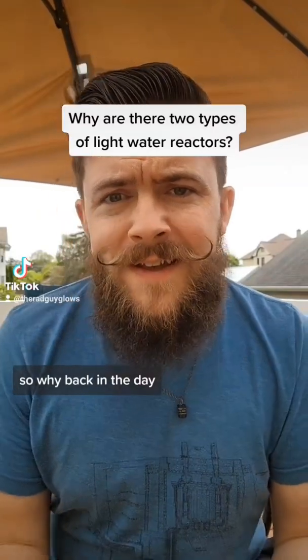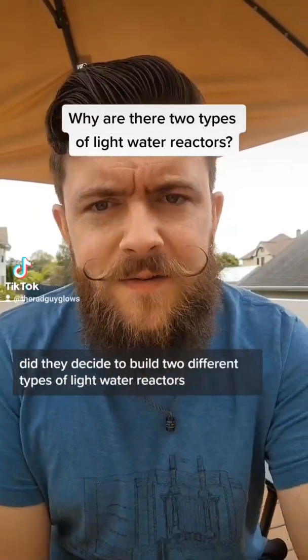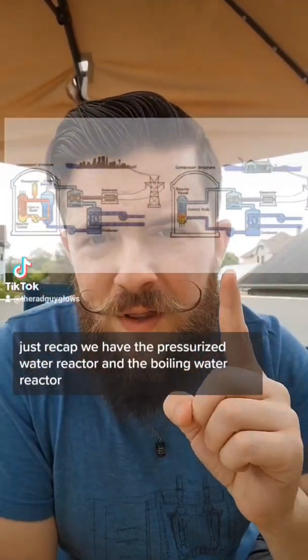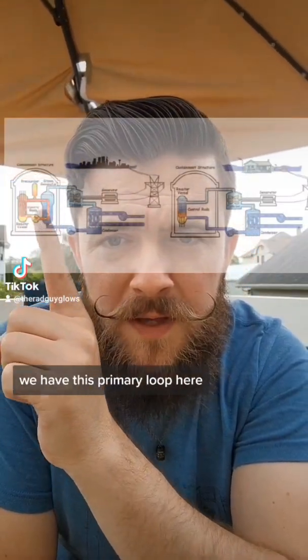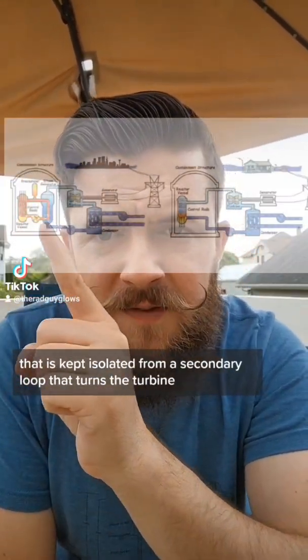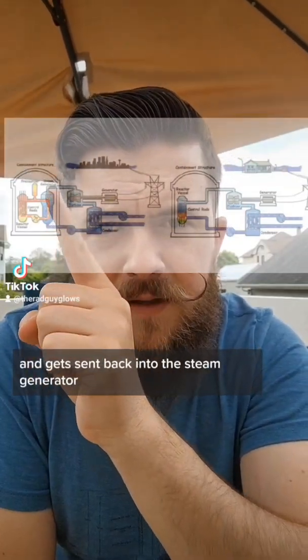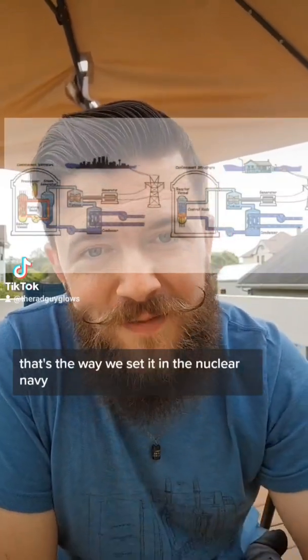So why back in the day did they decide to build two different types of light water reactors? Just to recap, we have the pressurized water reactor and the boiling water reactor. In the pressurized water reactor, we have this primary loop here that is kept isolated from a secondary loop that turns the turbine and gets sent back into the steam generator. Yes, I said turbine. That's the way we said it in the nuclear navy.